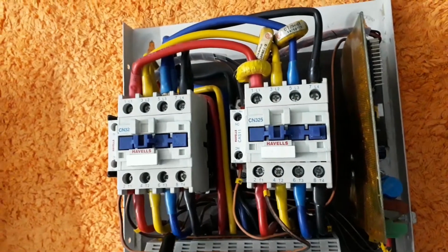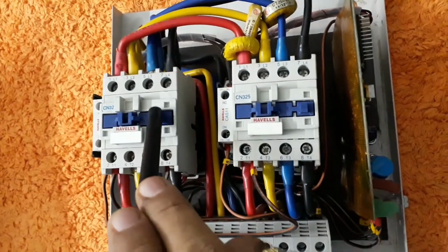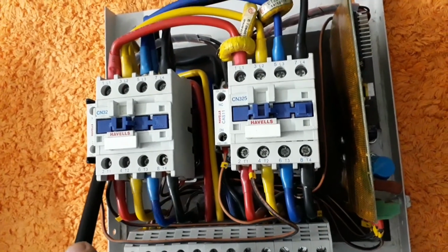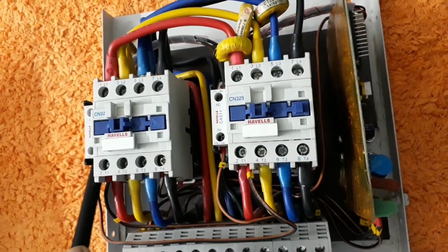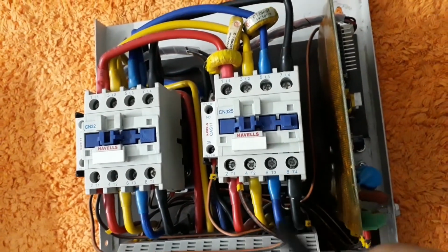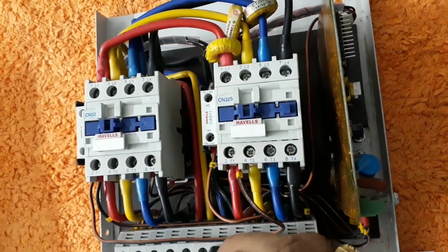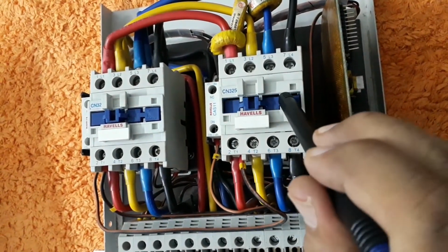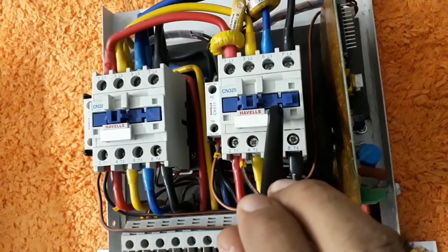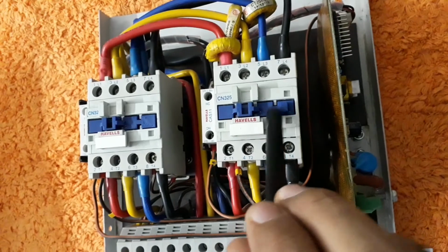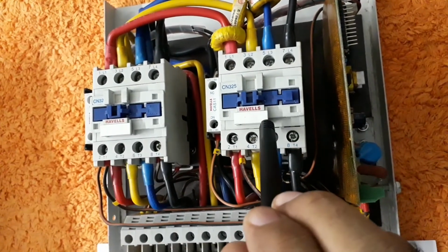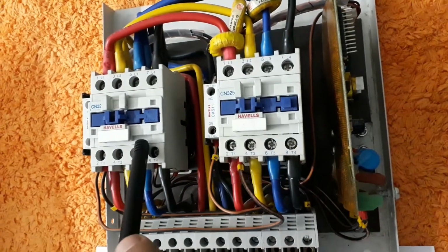The moment the mains goes off, this switch will come out and this will get operated. This will get on and this will make this relay work. The moment this relay works, the DG will get connected to our house line. So in any situation, only one of these relays will work. Both cannot work simultaneously, because when this goes on, this goes off, and when this goes off, this gets on. This is how it actually works.